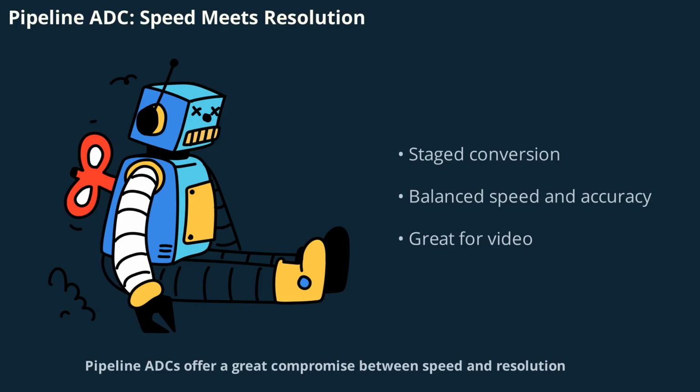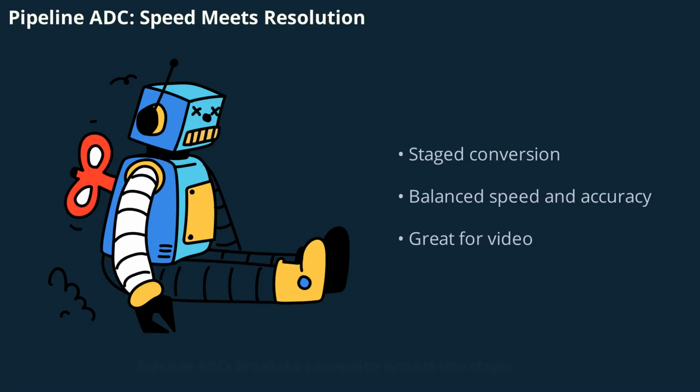Pipeline ADCs offer a great compromise between speed and resolution. They're commonly used in applications like video processing and communications, where both high speed and good accuracy are needed. Pipeline ADCs break the conversion process into stages, with each stage handling a part of the signal. This allows for fast, continuous conversions without sacrificing too much accuracy.